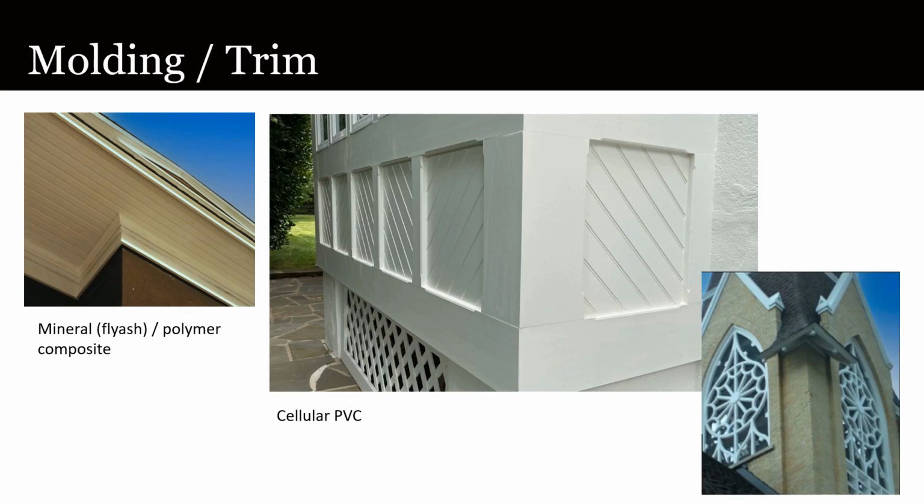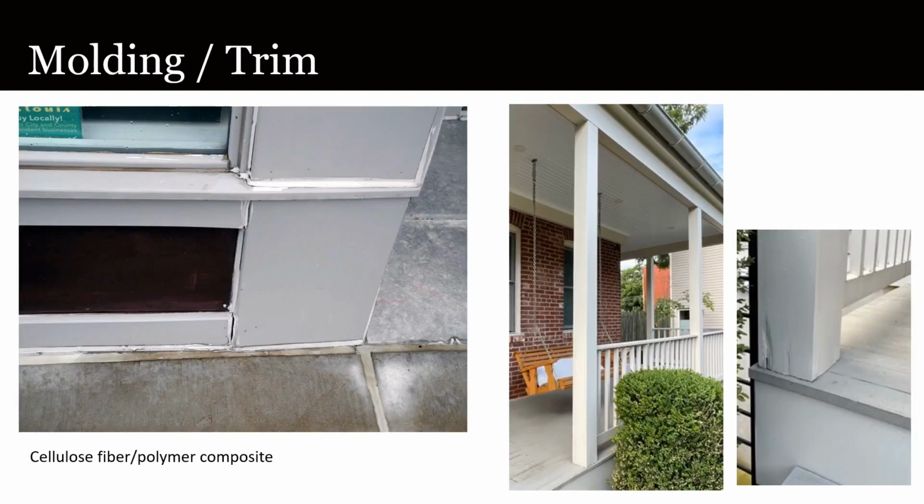Most of these materials are available as moldings, typical of what one can find in wood, as seen in the beadboard and molding that are of a mineral polymer composite used in the soffit illustrated on the left. The isotropic structure of cellulose fiber polymer composites can make them ideal where wide pieces of wood are needed and wood boards would cup and plywood would require a lot of surface prep to get a paintable smooth surface.